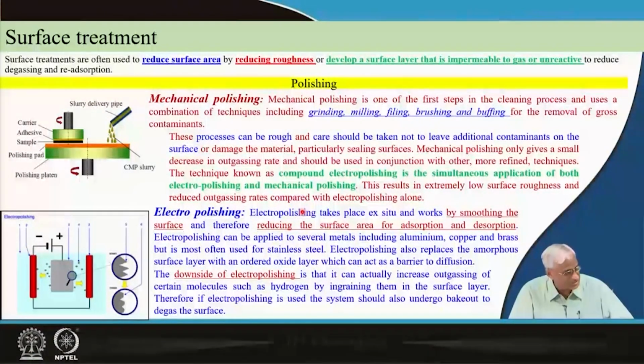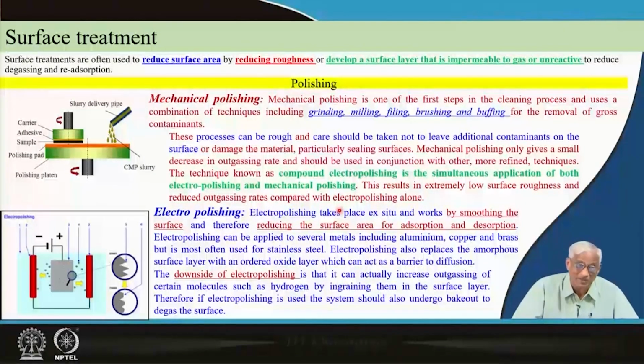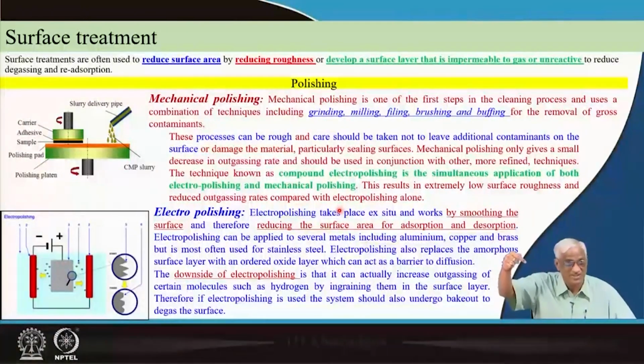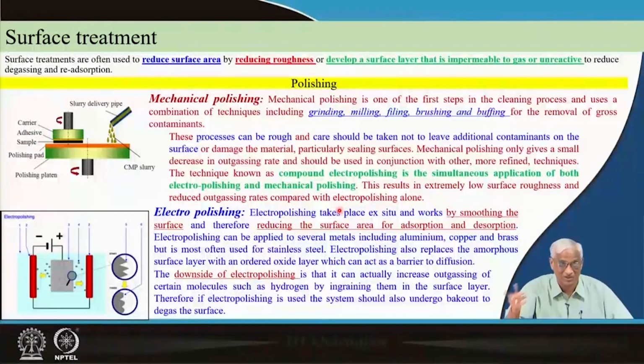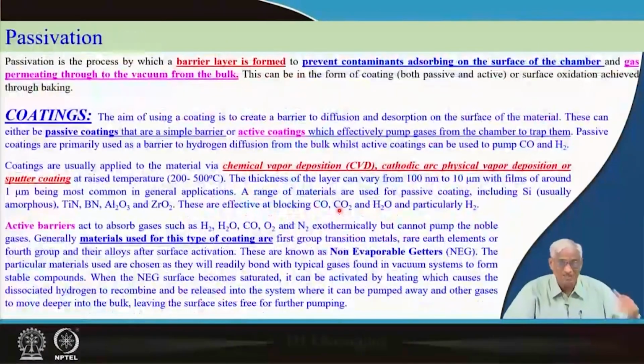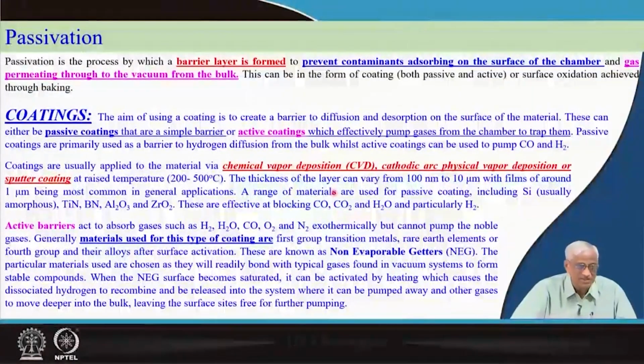If you can do both these things, you will get proper surfaces with less degassing, and desorption has to be minimum, whether things are happening or not. In situ monitoring will be done by RGA. If it is a high tech equipment, you can spend some more money to keep one permanent RGA leak detector. We will see that when we discuss the applications.